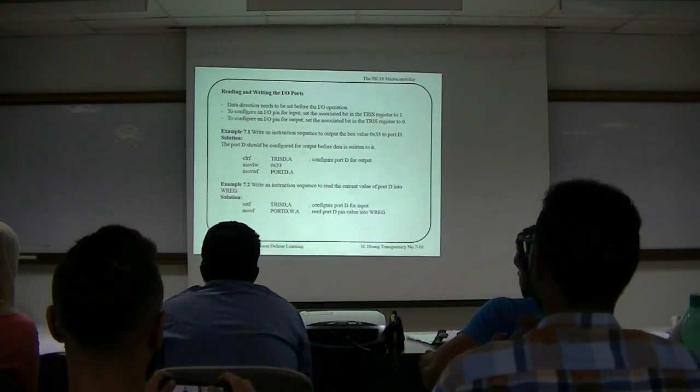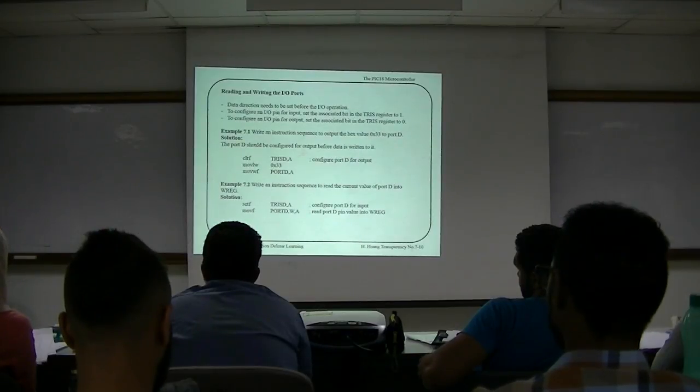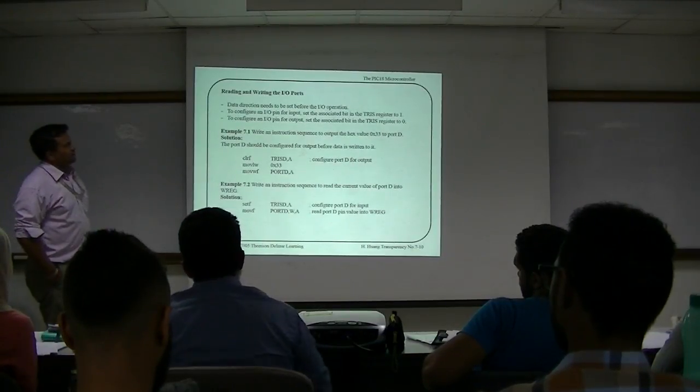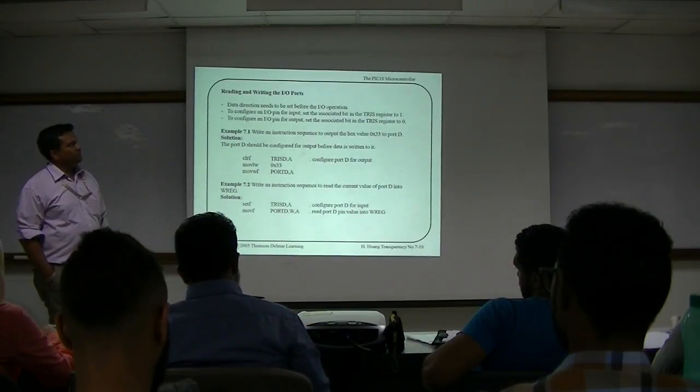Now the next part is how do we actually read and write the input-output port. So the first thing is data direction needs to be set before the input-output operation. To configure,